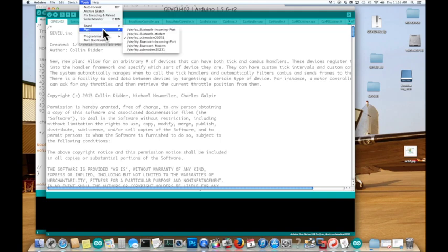Port is where you select your serial port. Now, I don't really know what to tell you on this. On the Macintosh, it's kind of like Linux. You have a devices directory and different devices. We know we're not talking to it by Bluetooth, so those four are out. That leaves us /dev/tty.usbmodem20231 or /dev/cu.usbmodem20231. Either of those actually works fine and will be the USB connection.